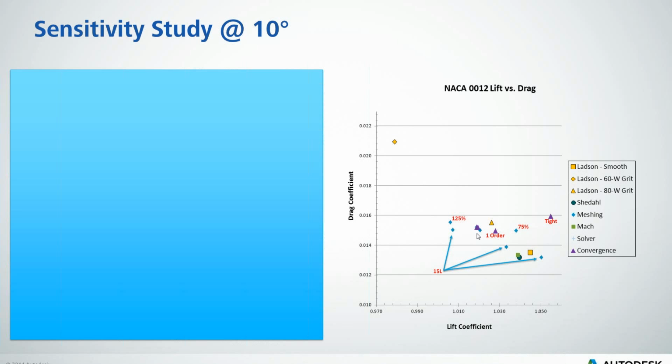So what you learn here is that, at least for this model, adding in 1 or 2 extra orders of magnitude and waiting for auto convergence, that is where it really starts getting close to being fully converged. Otherwise, you're left with the option of basically turning off auto convergence and over-solving a problem, which is usually what I end up doing, then setting something for like 10,000 iterations and letting it run for a day or so. Okay, so those are my different adjustments that I made.